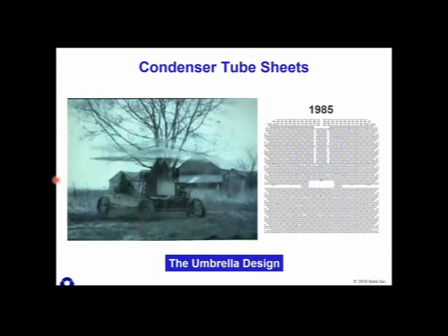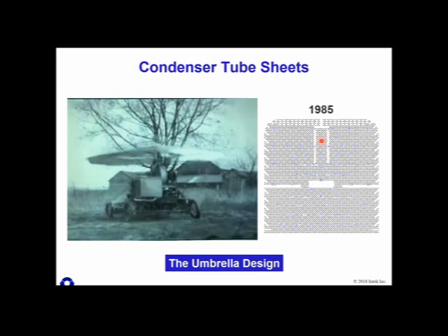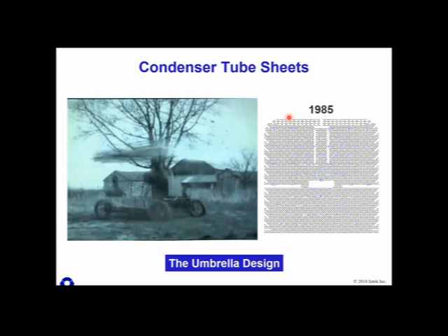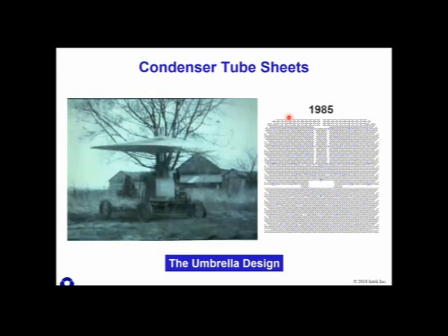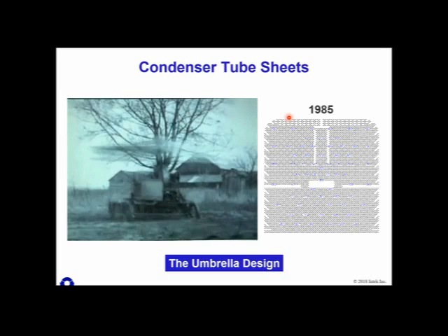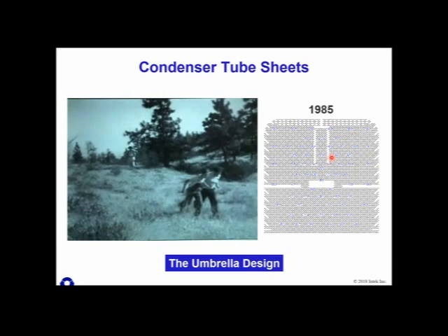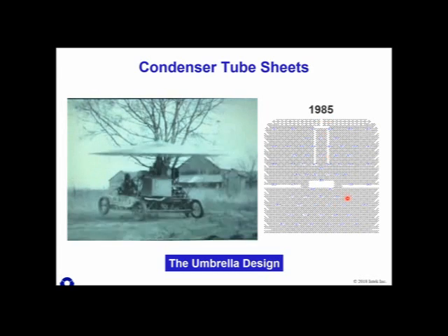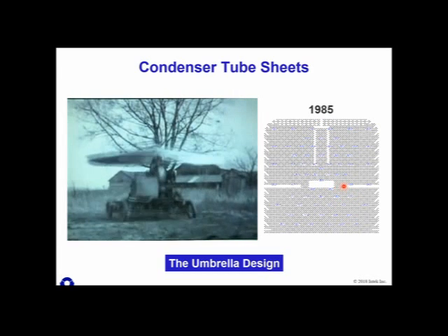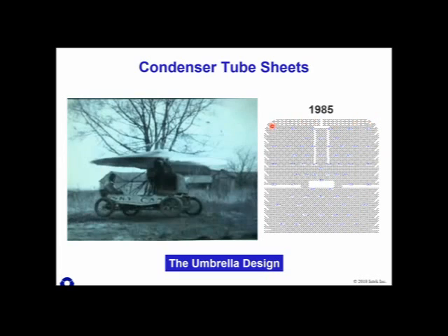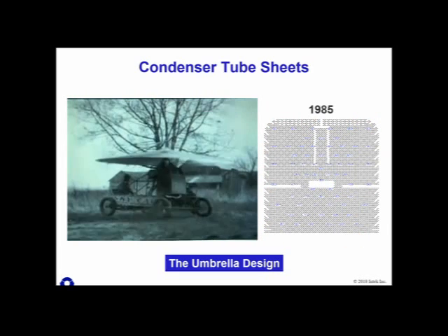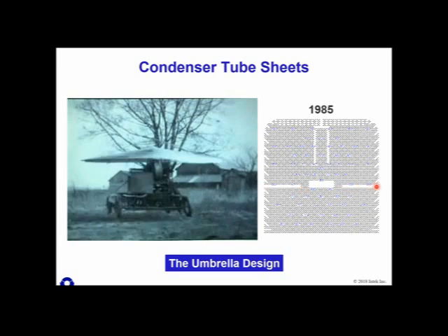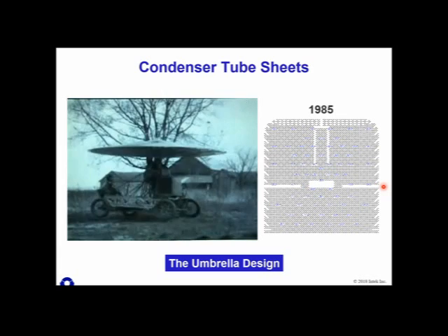So this bundle over here is an Ingersoll Rand condenser, original design. You would see designs similar to these coming out of SPX, both their Ecolair and Yuba lines. But you know, a common feature is this very tightly shrouded air removal section. You see these sections right here, very, very short lanes, by the way, on the periphery of the bundle. And then they have this lane and this lane here that they've made room for condensate management trays.